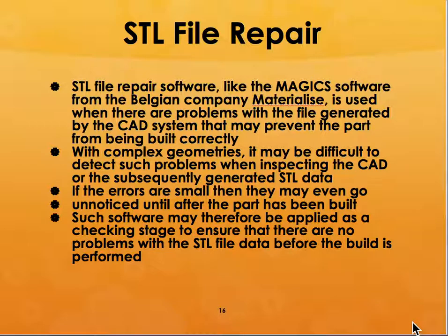So what it will do is create the accurate slice data. If the errors are small, then you may not even notice them until the part has been built. So you can use this software as a checking software to ensure that there are no problems with the STL data before the first part is built.